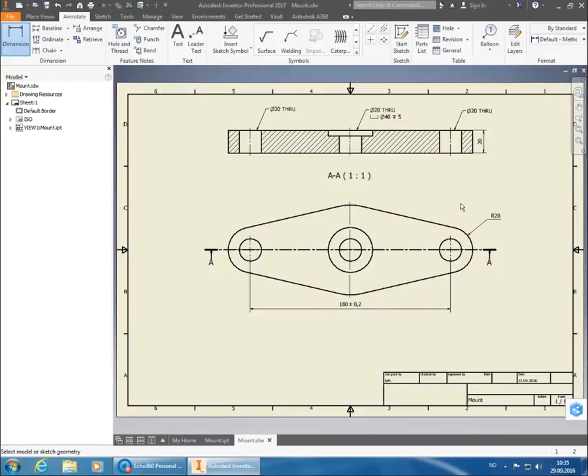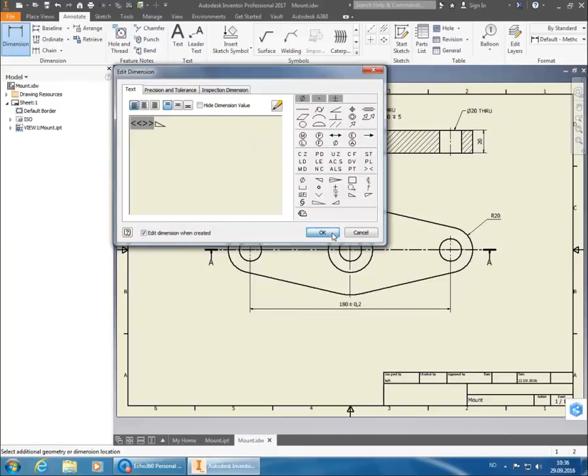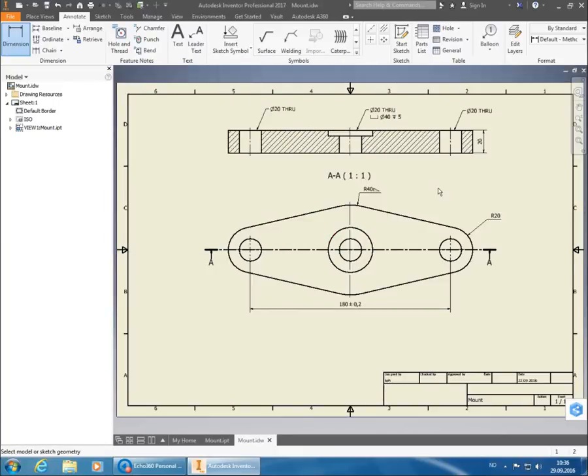Then we're going to place another radius, because we need to show what this top part here is. It has a radius of 40. So we need to locate it with the mouse so that we get just a curve up top there. We want to place a radius on it. And again, we have these symmetry lines. We have a symmetry line going over here, and we have a symmetry line going over here. So if I put a 40 on top there,